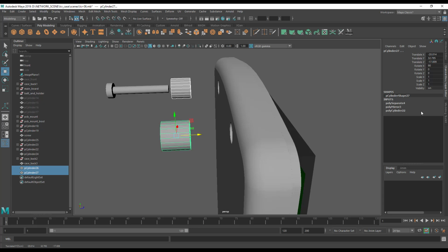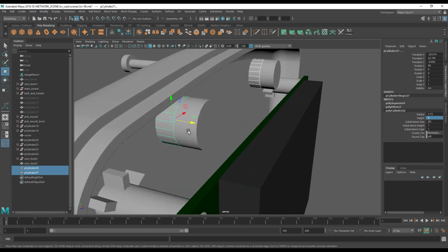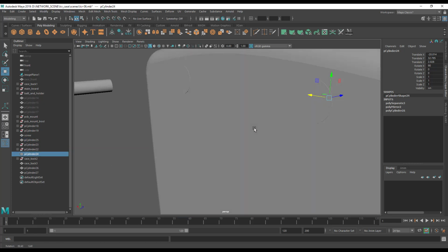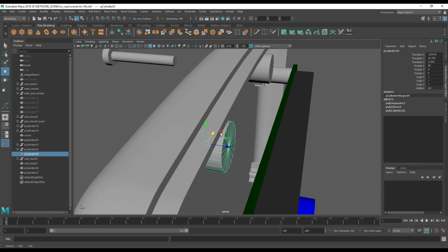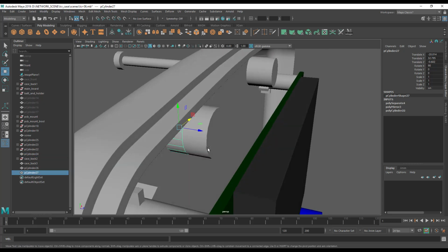And if we make a 5mm version of these, and we adjust this to the back, so that's 2mm through the case, and then it will be 3mm through these. These are 7mm, I believe. So these should be 5. That will allow the screw head to recess 5mm in. Yeah, that sounds about right.